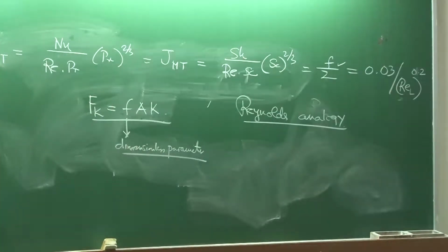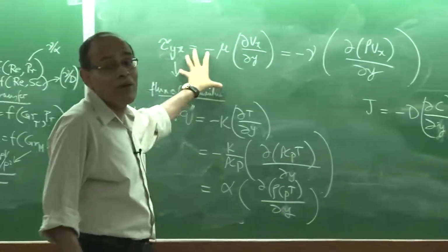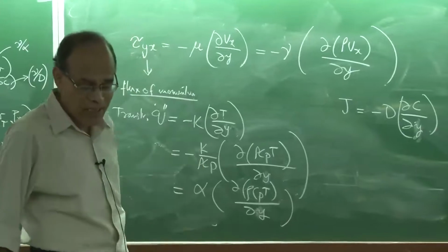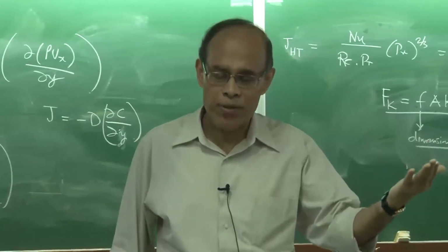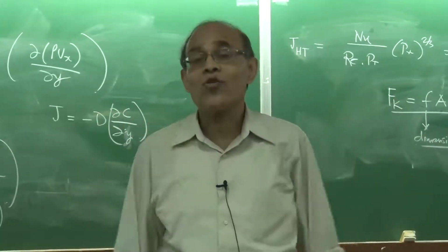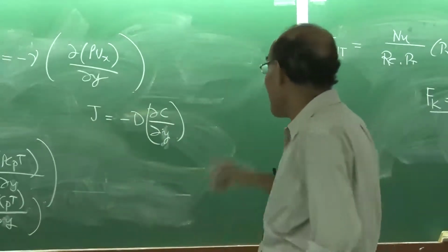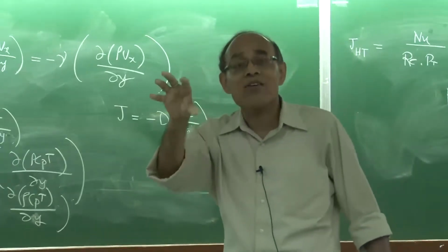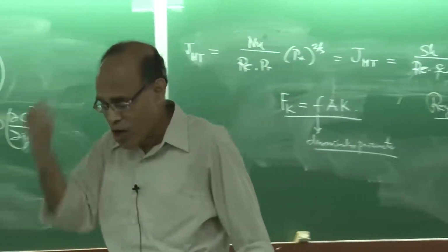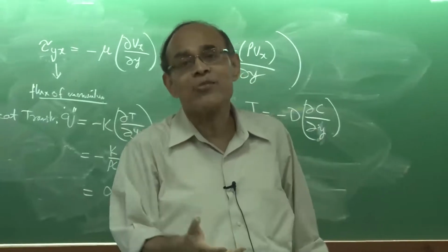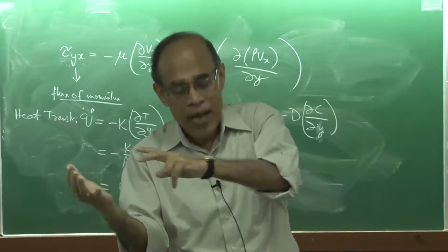Between heat and mass transfer, the beauty of it is that I have written two correlations, the Ranz-Marshall correlation for mass transfer and the Ranz-Marshall correlation for heat transfer, and you have seen that the correlations have forms which are exactly identical. So, what does this indicate? That the analogy tells us that for identical scenarios there can be one-to-one replication between the various dimensionless groups. So, one need not carry out a fresh additional mass transfer experiment. If one has done a heat transfer experiment, he can find out the corresponding scenario for mass transfer and vice versa.